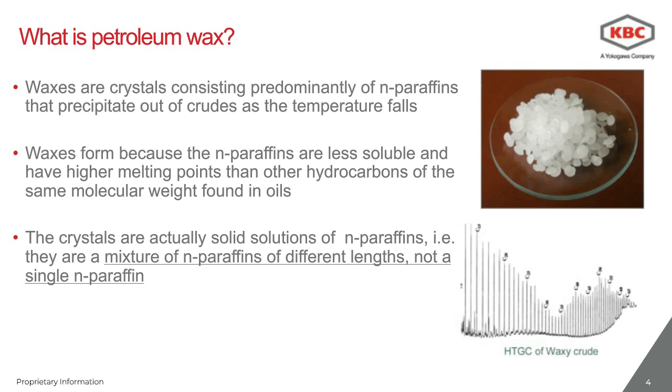Okay, what is wax? Waxes are crystals formed predominantly of N-paraffins that precipitate out of crude oil as the temperature falls below a certain threshold.